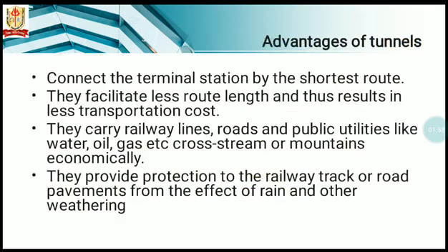Advantages of tunnels: they connect the terminal stations by the shortest route. They facilitate less route length and thus result in less transportation cost. They carry railway lines, roads and public utilities like water, oil, gas, etc. across streams or mountains economically. They provide protection to the railway track or road pavements from the effects of rain and other weathering effects.